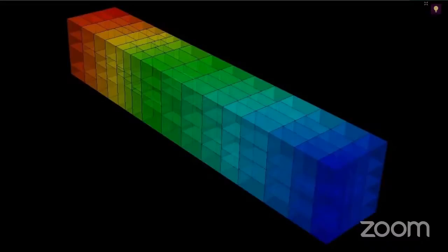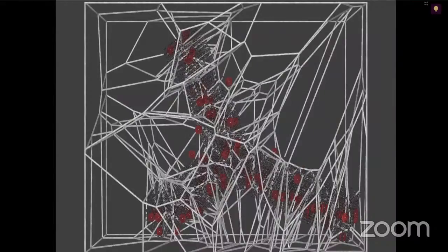For example, this might be the final result of a staggered grid decomposition, while this might be the result of a Voronoi-based decomposition, where the larger red beads represent these creation points that should move in the direction of the work, so that the Voronoi cells might or should divide the work better, with a better surface to each other than normal rectangular domains.